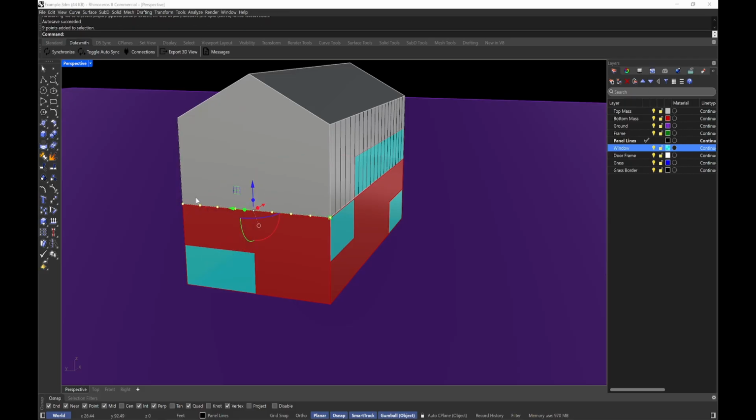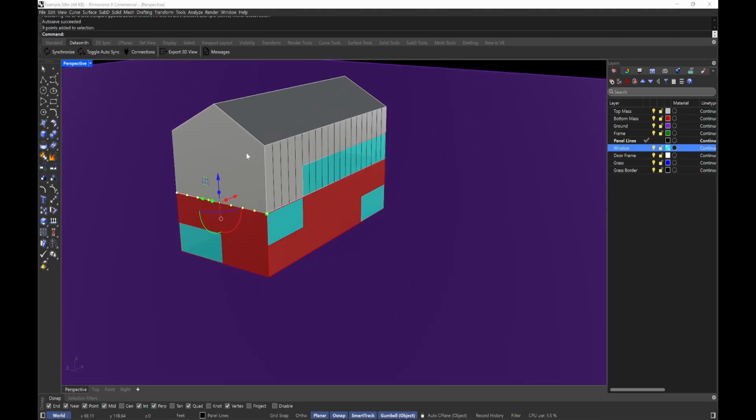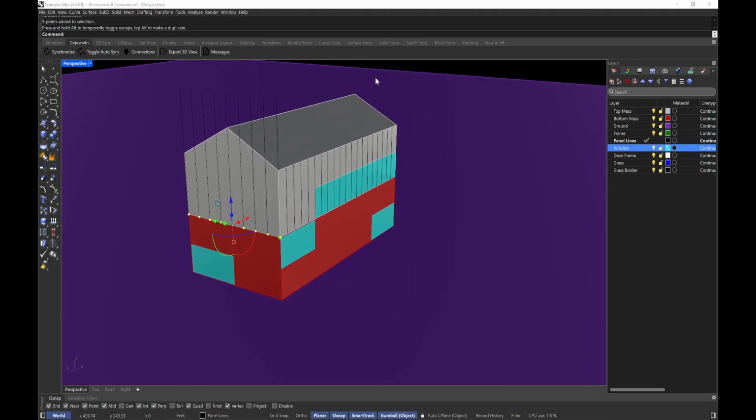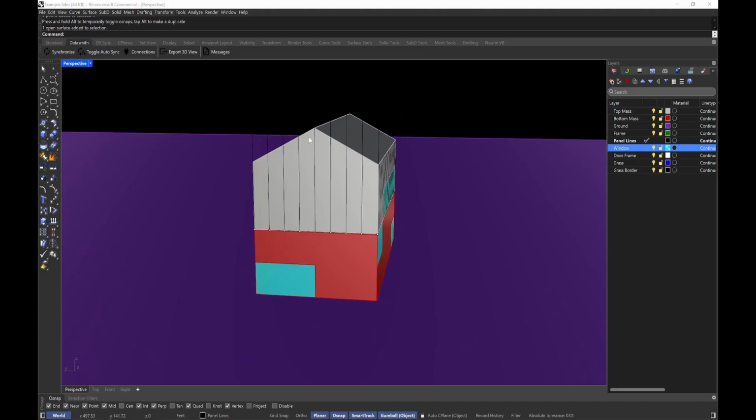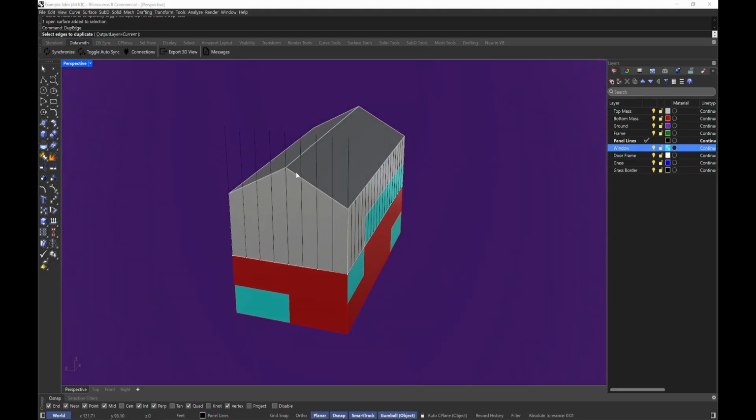And by default, for the divide command, it'll group it for you. So these points, I can just take them and extrude them, right? So I can take these points and just go like that, you see? And I can trim these points too if I just do dupe edge, or I can split them, you know, it doesn't matter. I didn't need to dupe edge of this. I could have just trimmed it from the actual mass, but I just want to show different commands.